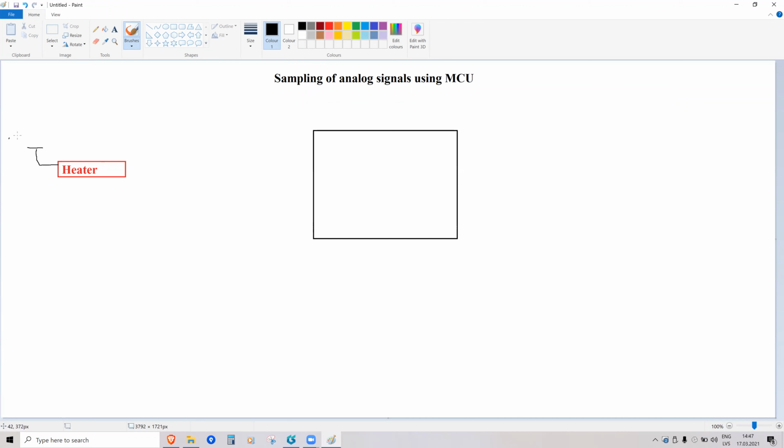Usually high voltage, maybe it's 230 volts, or in this case, we'll use low voltage to simplify the circuit, but maybe it's, for example, I don't know, 12 volts. I'll change it to 12 volts DC, some heater, and then you would normally use a MOSFET with which you turn on and off the heater depending on the temperature.